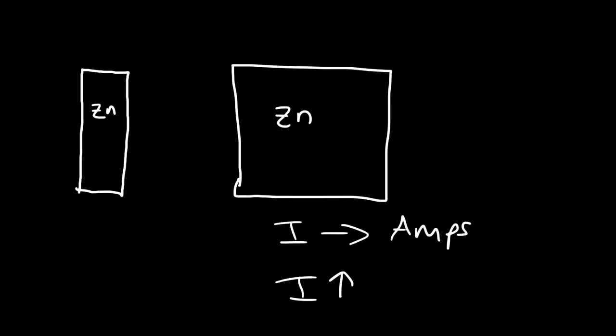So what some batteries have is, instead of having just a metallic electrode, sometimes the electrode can be pressurized into a powdered form. So let's say if you use a powdered form of zinc or a powdered form of graphite as an electrode and you pressurize it, you can get a lot more surface area doing it that way. And so you can get a battery that can deliver a high current.